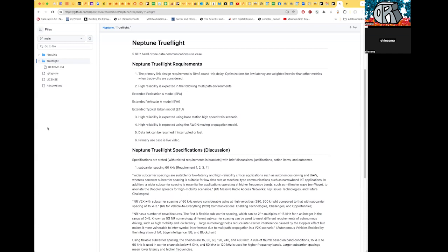And it really doesn't make much difference whether these things are caused by the environment and just nature and the configuration of the world, or by jammers, like people actively sitting around trying to spoof what you're doing. So all these high reliability things, that's where I feel OFDM really shines. It's more compact because it uses coding to allow the subcarriers to be spaced much closer together, but it spreads the signal out over a range of subcarriers.